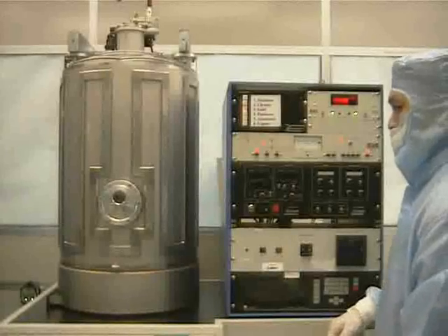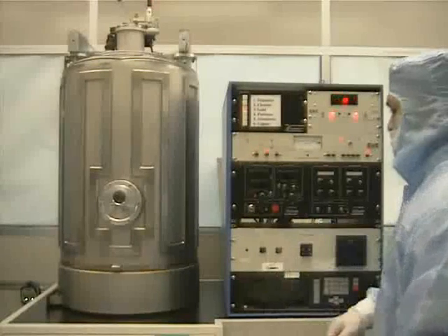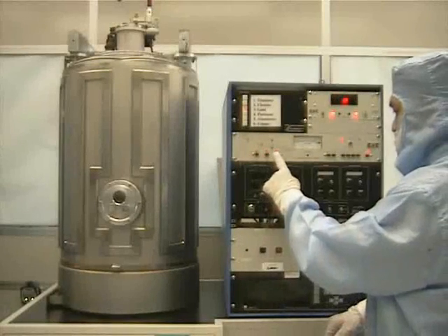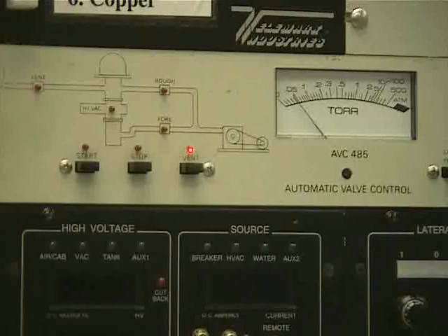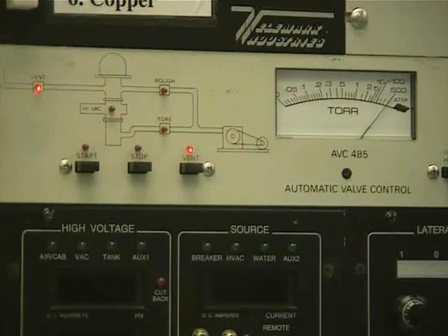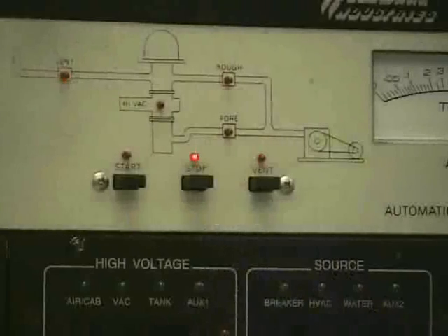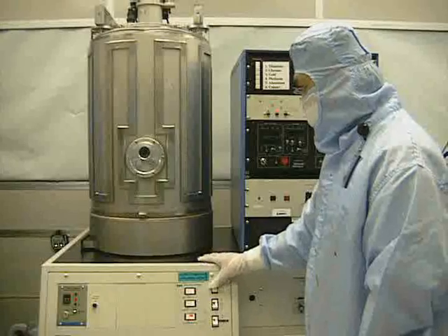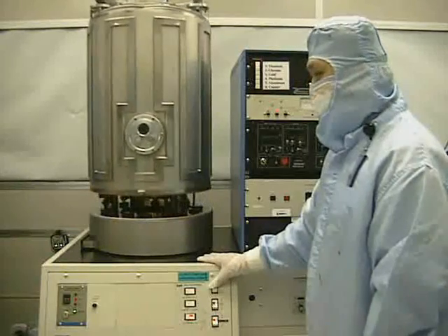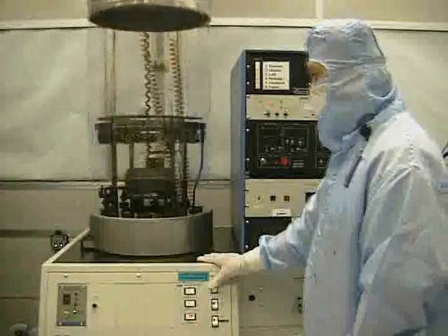We first want to go to the automatic valve controller and press the stop button and then the vent button. We will then wait a few minutes for the system to vent. Wait until the needle on the chamber pressure gauge reaches the right side of the display. We can tell the chamber is vented by either waiting for a clicking noise, a hissing noise, or by actually feeling the nitrogen gas coming out of the chamber by the seal. Once you hear the clicking noise, push the stop button to close the vent. Then press the hoist up button on the hoist controller in order to raise the chamber all the way.